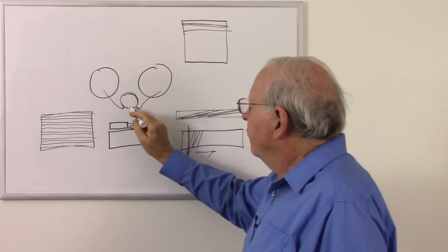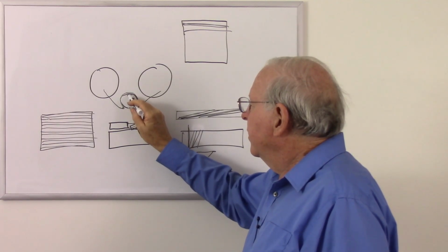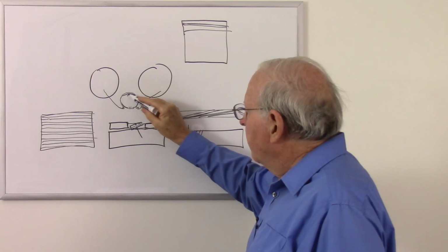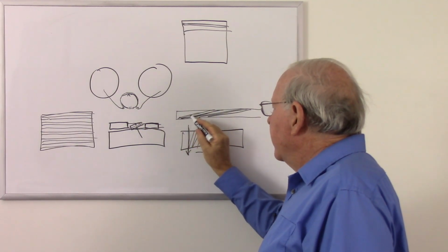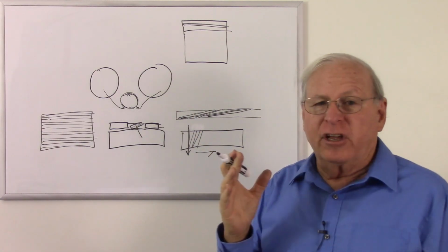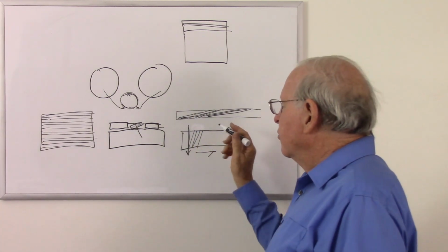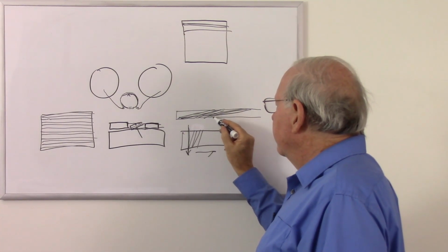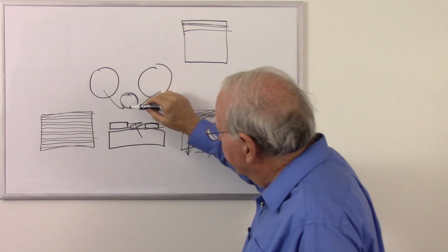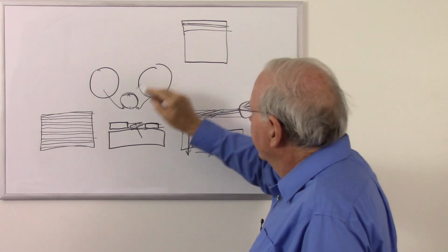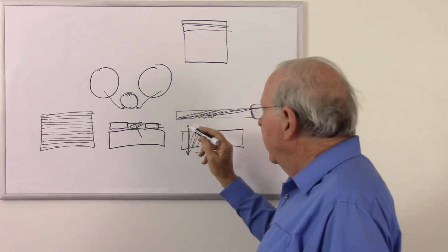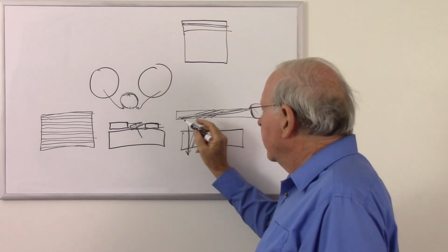So the spinning drum had two heads on it. One would scan an even line, and just as it was finishing the even line, the other one would be partway through an odd line, so we'd get these very close, maybe partially overlapping. In fact, in VHS they do overlap, and they use a little trick to eliminate interference between them. And I'll mention that in just a second, but the idea is that we have these two spinning heads scanning even line, odd line, even line, odd line, and recording that information. And back to the VHS, those lines were so close together they actually overlap.